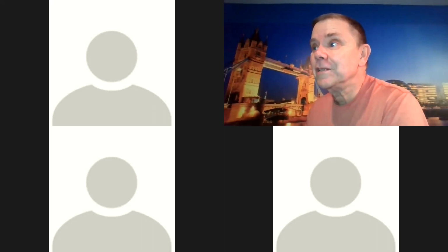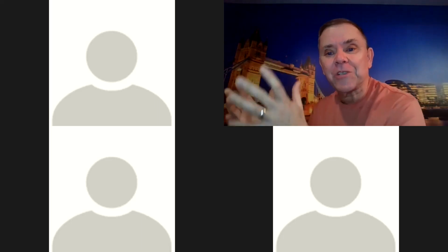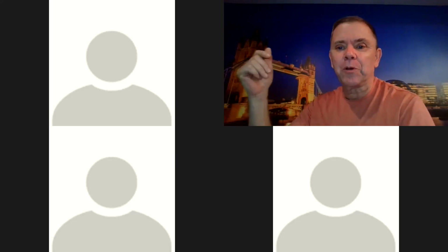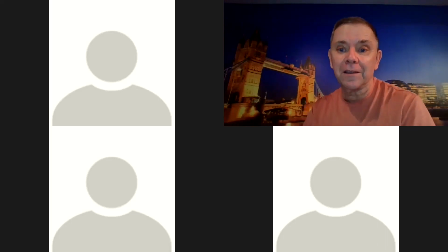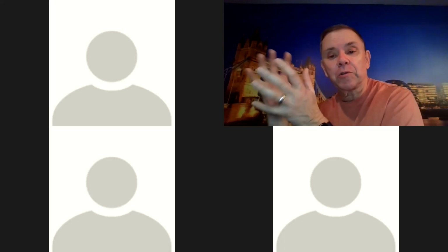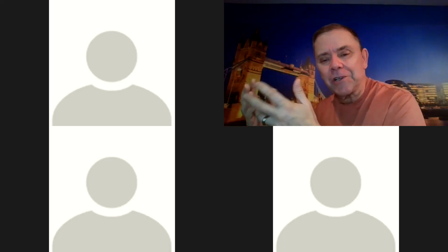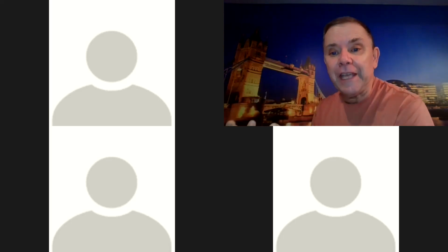This is working really well, you guys. This is looking good now. So you're starting to get the idea. What we're trying to do is take the narrative that's been given to you about how it works, and deconstruct it into all the circuit elements: the upper limit switch, the lower limit switch, the push button up, the push button down on the top floor and on the bottom floor, the brakes, the motor up and the motor down. So we're trying to find all these circuit elements and we're going to give them names, right?